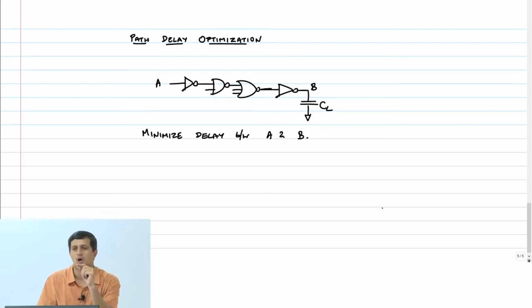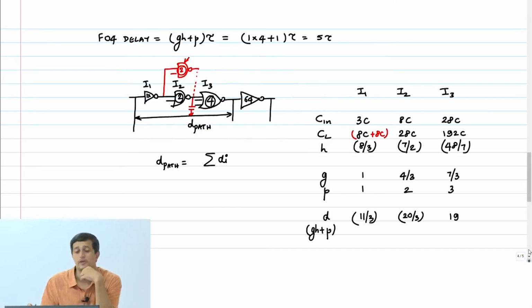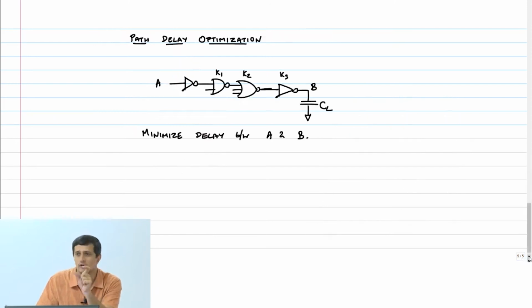Okay. So now clearly, if I went and chose my variables as, let's say, my variable was the size of the drive strength of the NAND gate, let me call it K1, this as K2, this as K3. Suppose I did that, then you already saw in the previous case, you have to put in a lot of effort to calculate the input and output capacitances because it depends on the topology of the gate, right? So that's not very useful. Not very useful and slightly more cumbersome, right? The delay expression we have derived is actually very, very compact and nice if you choose your variables correctly.